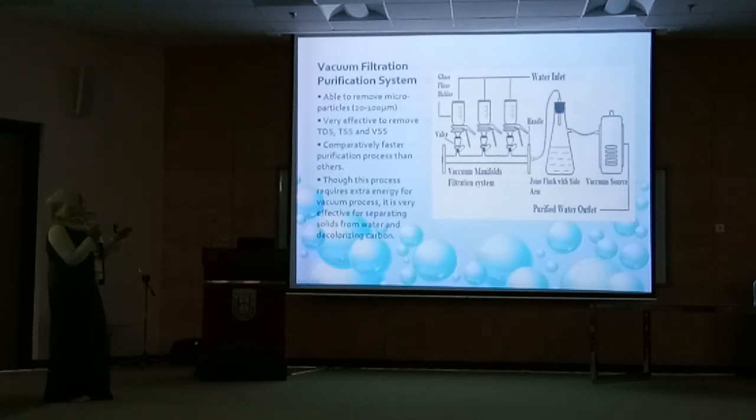Vacuum filtration, yes, this process needs some power consumption, but it's really effective to lower down the TDS, TSS, and VSS, and it's able to remove microparticles 20 to 100 micrometer. This process requires energy, but it's very effective for separating solids from water and decolorizing the carbon.